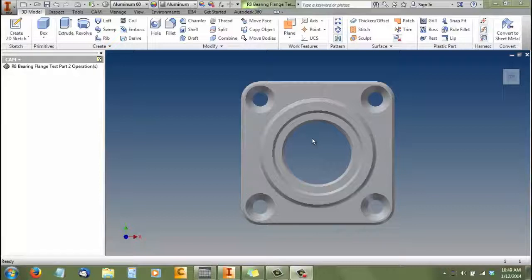The first thing you need to do when you want to put toolpaths on a part is to define the coordinate system. In G-code, the coordinate system is defined by a G-code command called G54. It's very popular. I believe G52 through G59 are different work coordinate offset positions. Typically, you machine to G54, and that's what we're doing here. We're just doing a single work coordinate system for all our machining.